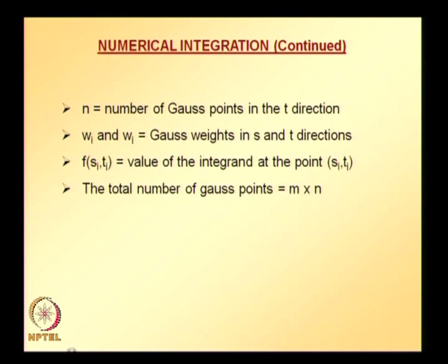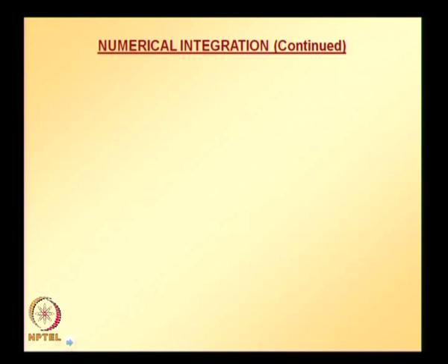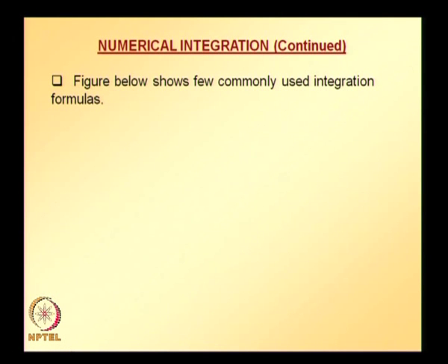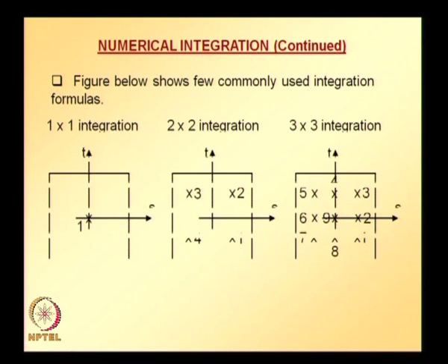So, for completeness they are repeated here, and before that we will see a few commonly used integrations for the two dimensional case. Here one by one integration is shown, that is, along the s direction one point is taken, and along the t direction also one point is taken.